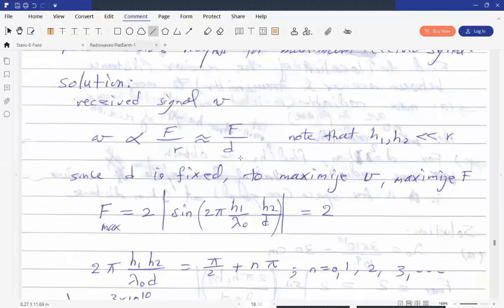Once you put the equivalent radius, you use straight rays. No refractive index, no epsilon. We do not use epsilon r. The actual radius of the earth, r earth, is equal to 6,378 kilometers.